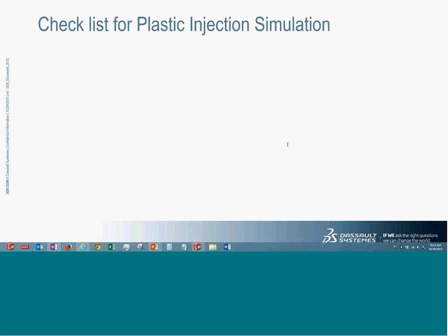I heard that in 2015, we have been given an option by which we can export the stresses in the cavity after cooling down, or at whatever temperature they are, to a structural analysis. So now we can export those stresses and do further stress analysis. It is nothing but the warpage. So it can be done at the moment. If possible, I will try to show you how we go about it.